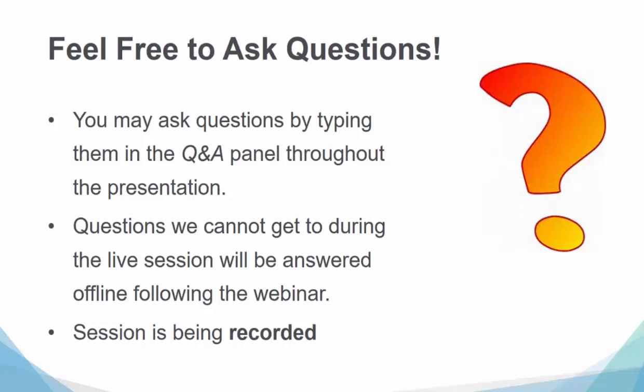Okay. And by the way, everyone, I thank you for the good questions. We've got a few more coming in here, Dave, so we've got plenty to talk about. Can a printed core have a texture put on it, acid etching, that kind of thing? As far as I know, yes, it can. I've been told we can get a Class B surface finish on a printed core, which is pretty good for most molds. Maybe not ones coring Class A, but it seems that we can do most of that and certainly acid etch it too, from what I've heard.